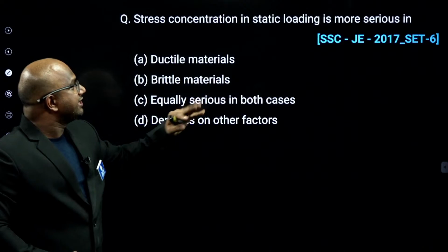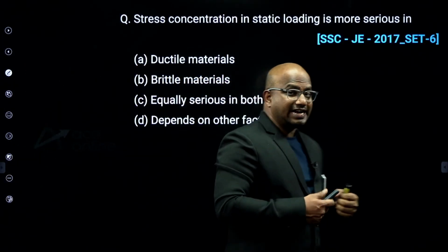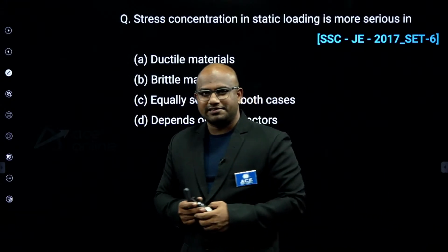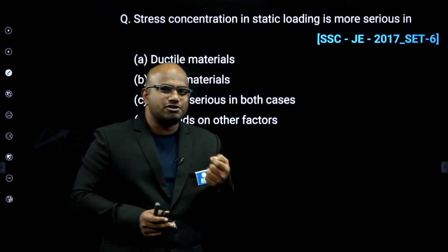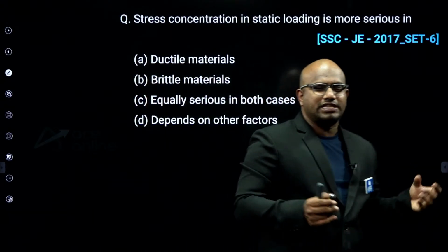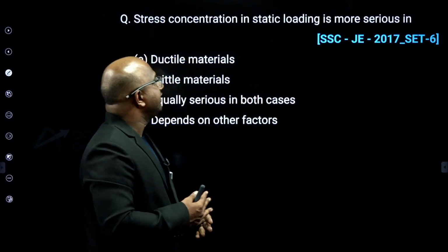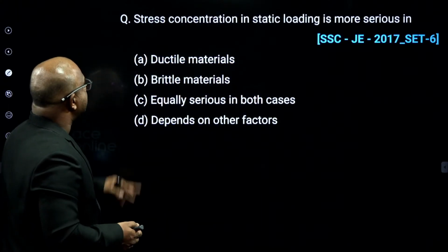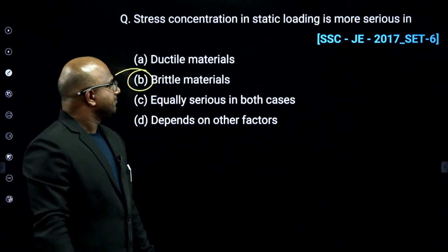Now, the stress concentration under static loading is more serious in? Tell me, sir. Generally, guys, for ductile material, localization of stress is not that serious. For brittle material, it is very, very dangerous if it is subjected to static loading. The answer is option B, guys.